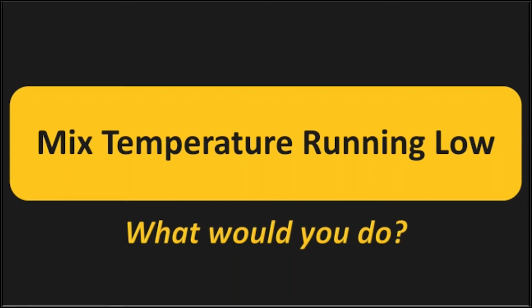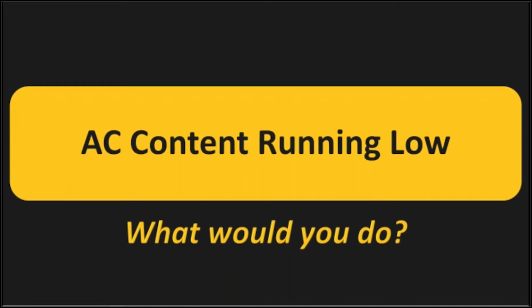And with the 3077 and the 3076 specs having a much bigger emphasis on temperature now, both mix temperature before it goes into the paver and behind the screed if you're running a camera, there are a lot more things going on now than there used to be. So temperature is important. We need to stay on top of it. All right, let's move on to the next one.